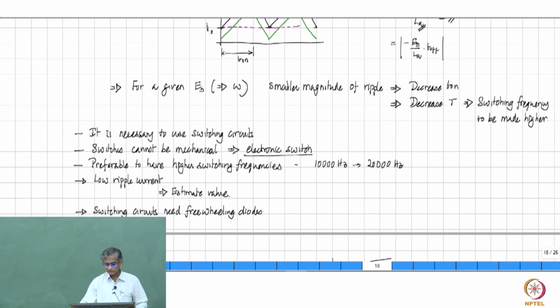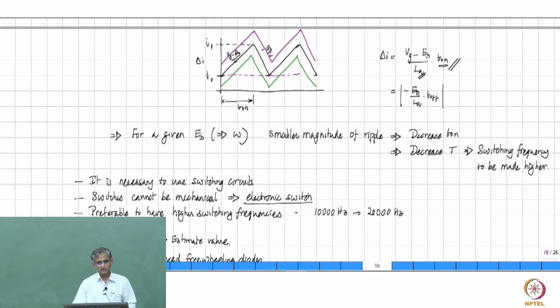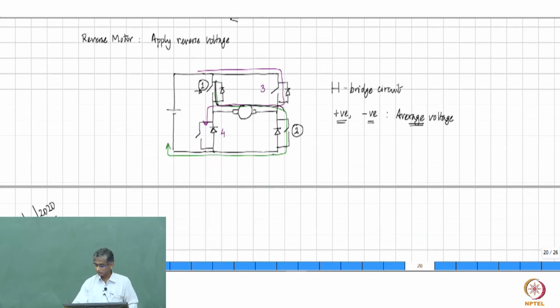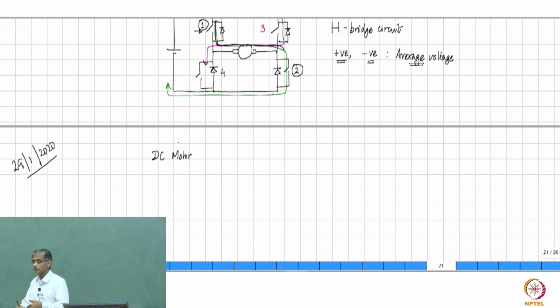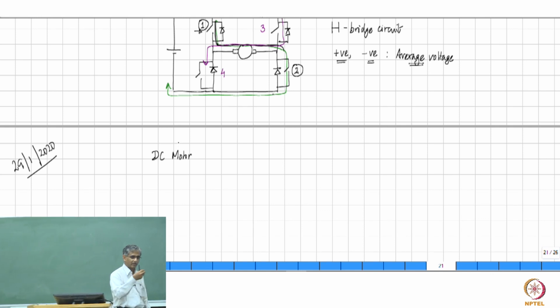So in order to determine what the average value is going to be, you need to understand that this input or applied voltage is being given to a DC motor, and we need to understand what the DC motor will do. The DC motor or any other motor will always attempt to meet its load requirement, right? So if the motor has to rotate a particular load demanding a certain amount of mechanical torque at this particular RPM, it will attempt to generate that, and it is from that you can determine what the average value should be.